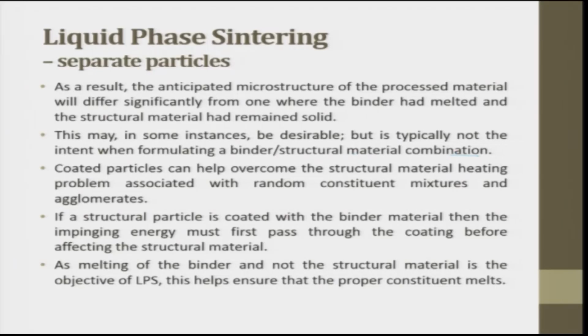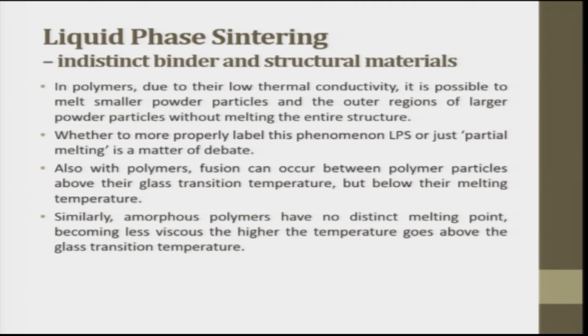The coated particles can help overcome the structural material heating problem associated with the random constituent mixing and agglomeration. If the structural particle is coated with a binder material, then the impinging energy must first pass through the coating before affecting the structural material, as melting of the binder and not the structural material is the objective of LPS. This helps to ensure that the proper constituent melting happens. So, the last part of the powder is distinct binder and structural material.